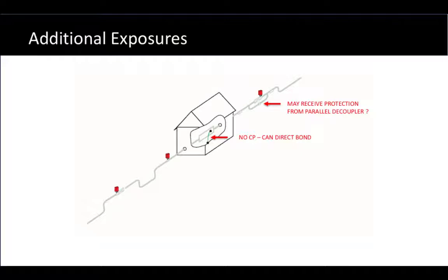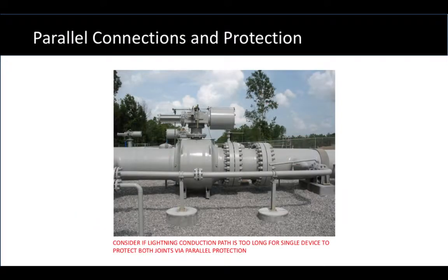And this effect of inductance interacts with fast-rising waveforms, such as from lightning, where you can still end up with a high voltage across the point. And we wouldn't want to leave a point unprotected and then still have it flash over due to a fast-rising waveform like lightning. It won't happen with AC faults, but it could with lightning.